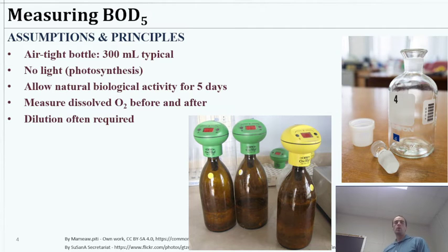Okay, so when we're talking about BOD, and maybe you noticed this in our book or problems, we often put a little 5 subscript here. That's referring to a standard convention of using 5 days to test biological activity. So BOD5, that's how much oxygen was demanded by the water in 5 days. Okay, so that's our assumption here when we say BOD5.